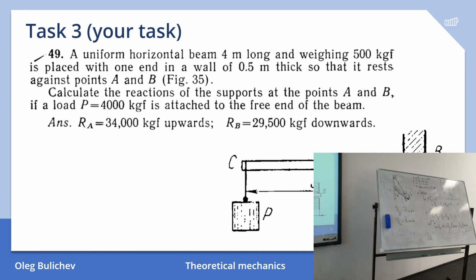I think we'll receive three equations just like this, and it will be solved. I guess not, in any case, because we have only one body. Actually, it's easy. You can use the third form of the equilibrium condition: torque at three points. You can take it at point C, point A, and point B. Super easy.